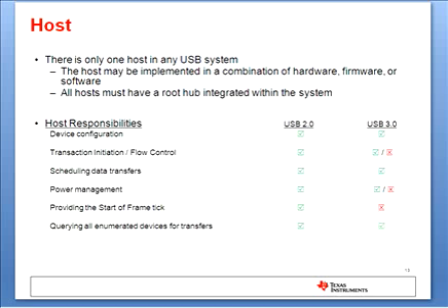Hosts are also responsible for transaction initiation and flow control. One exception to this is with the 3.0 standard, devices can also initiate transactions. Regardless of who initiates the transaction, the host is responsible for scheduling data transfers on all the devices on the bus. The host is also responsible for power management on the bus.